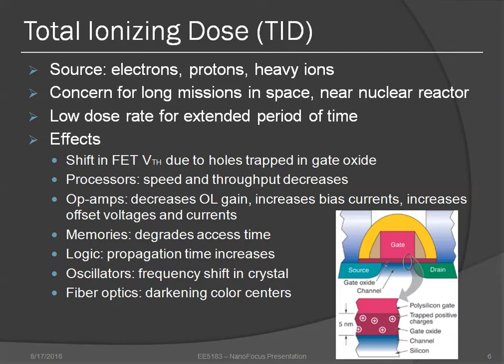If you recall from quantum mechanics, the energy from a photon can cause an electron to jump from the valence band into the conduction band, and in the case of FETs, the electron gets whisked away by the electric field. That then leaves more holes than electrons, or a positive charge, in your oxide layer. The holes end up trapped in the insulator, and TID is also caused when high energy electrons traveling at high velocities knock other electrons out of their bonds, leaving holes as well.